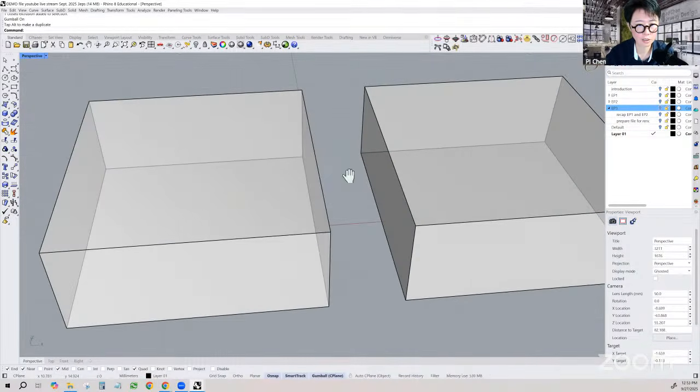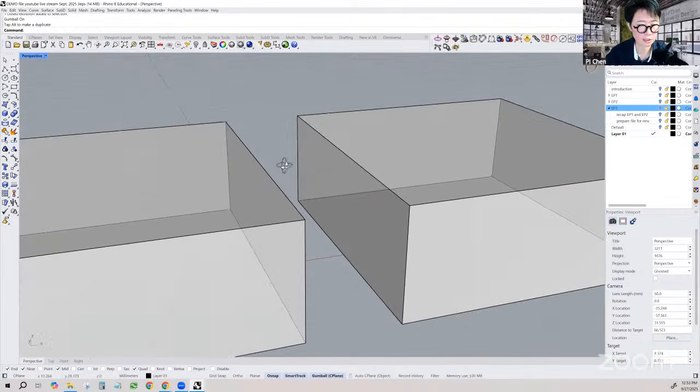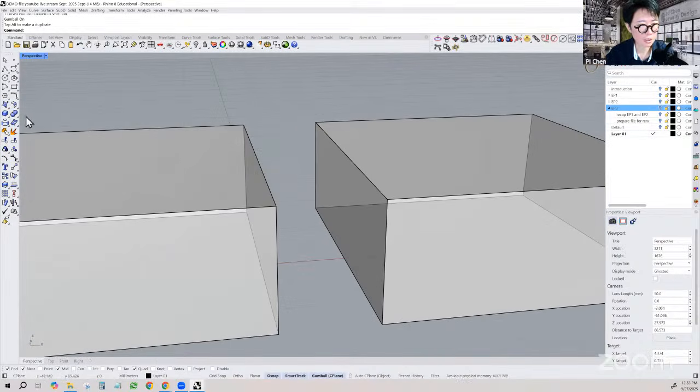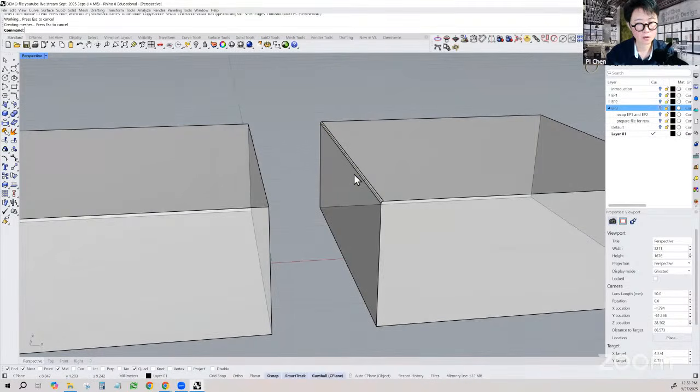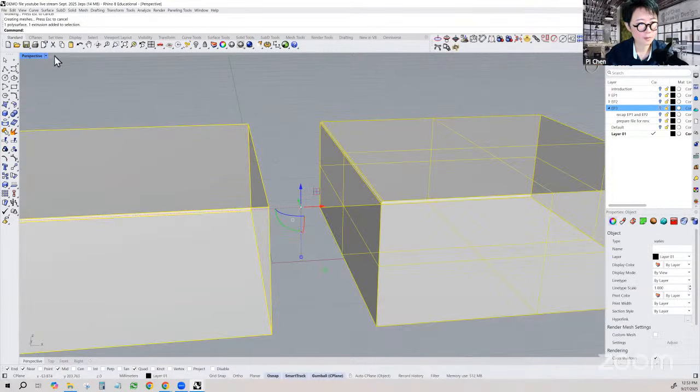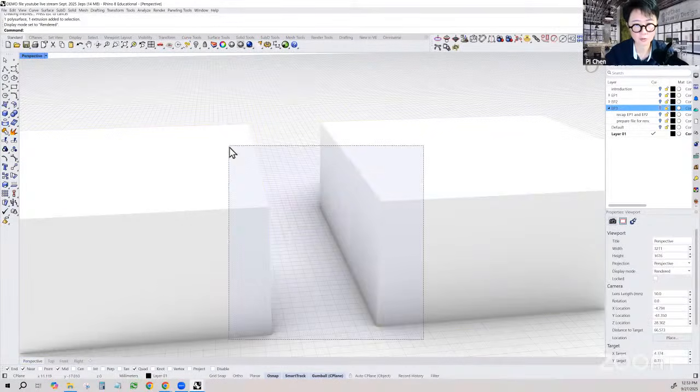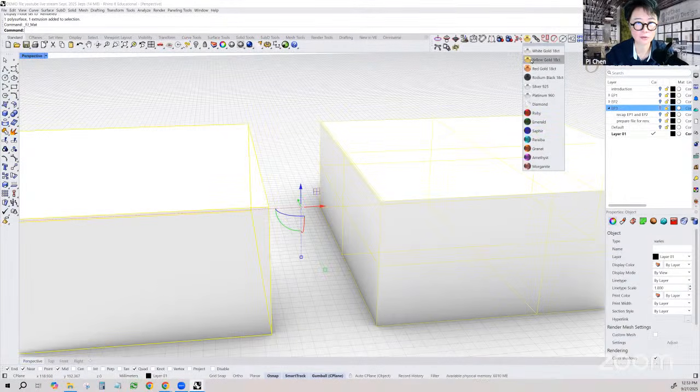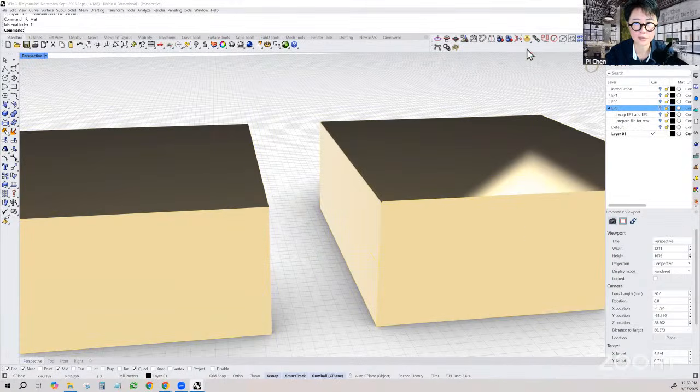We want to look at those two edges here, right? The first one has really sharp edges. The second one, I'm just going to give a very small fillet, like 0.2 millimeter. That's super small, right? Okay, and then for both of them, let's take a look at the render view. The white doesn't show much. I want to see something in the reflection, so I use iJewel really quickly to get it into this.